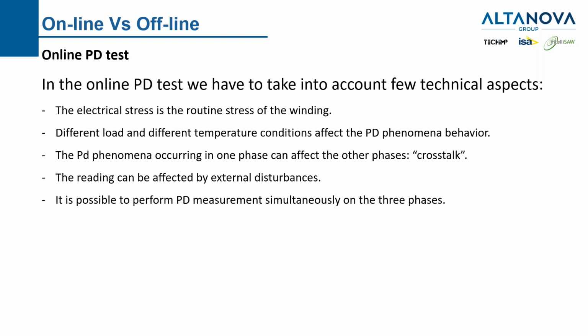Another good thing that we can do with the online PD test is that we can perform the PD test simultaneously on the three phases, and we can take advantage of the different phase shift between the phases to make the analysis.